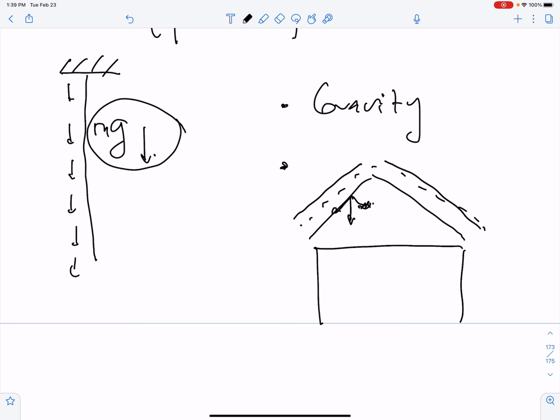So for truss elements, we're only going to be considering tangential components going forward, okay? And then when we start introducing more complicated elements, like beam column, it'll be bending, and it's precisely the bending part of the equation that will be able to handle transverse loading, okay?